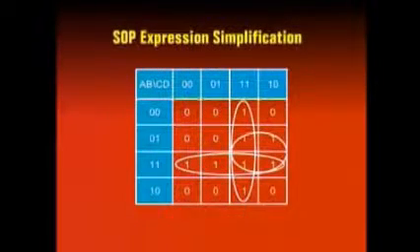An appropriate way to implement the adjacent 1's detector circuit is to simplify the SOP or sum of product Boolean expression represented by the function table and then implement the circuit based on the simplified expression. The function table information is directly mapped to a 4-variable Karnaugh map.